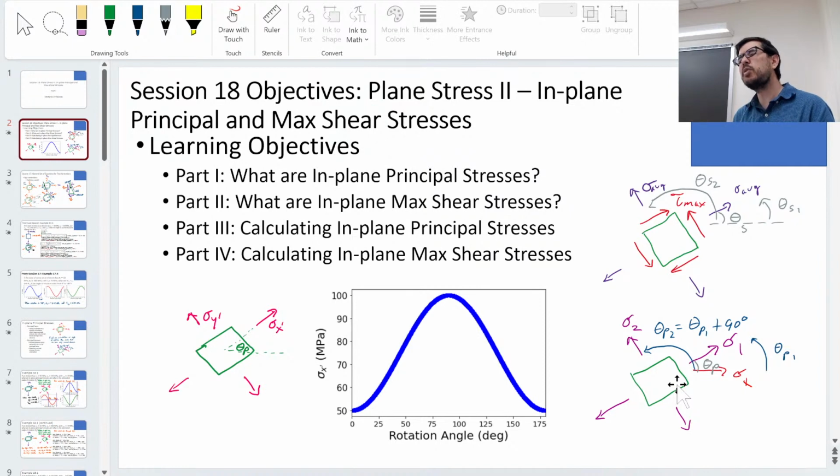You'll also see that when we do the absolute maximum shear stresses, okay, we care about the third dimension a little bit, and so there's often going to be a sigma 3 as well. And so sigma 1 is usually the largest, sigma 2 is usually the second one, and sigma 3 is often 0 for our cases, okay, or sigma 2. So they're interchangeable, but the point is that those three are the principal stresses, or maximum normal stresses, okay. And then the shear stresses, well, you might see something like a tau max, all right?